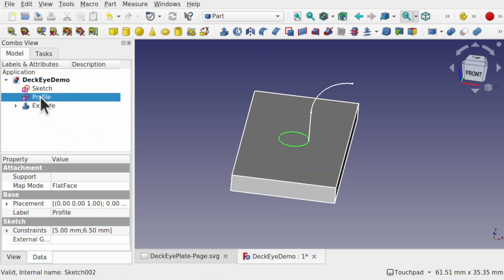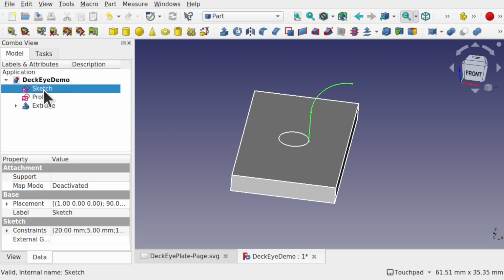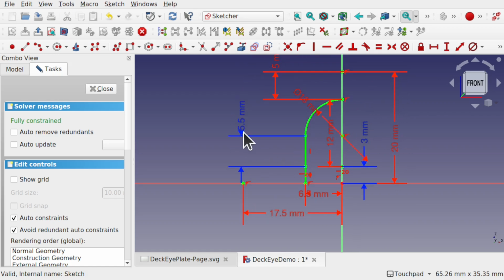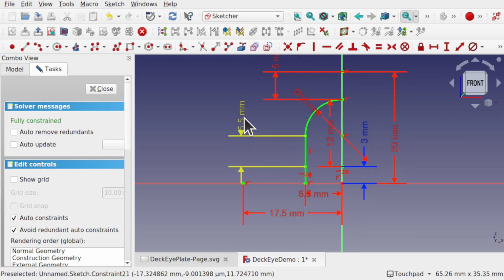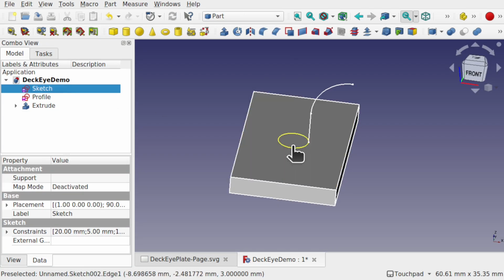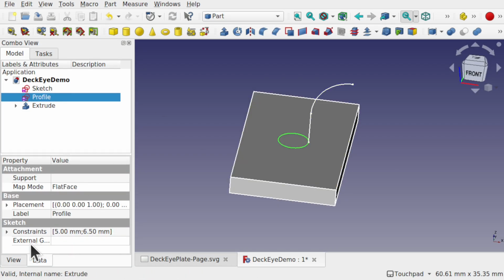We're going along the same revolve workflow as before, and we know from that sketch we've got to move this up 5.5mm from the actual base. So click on that profile, come into the placement. It's not attached.